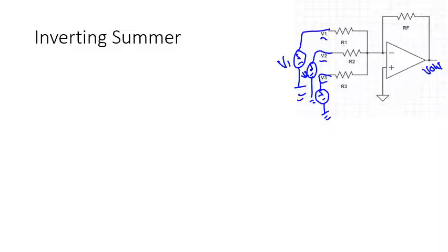And I want to see what happens here. Well, no current goes into my op-amp. So if this current is 0 and I have no resistance, this is also 0 volts. And this is 0 volts because I have a feedback loop. It means my inverting input will be held to my non-inverting input. Now let's write some equations for current.